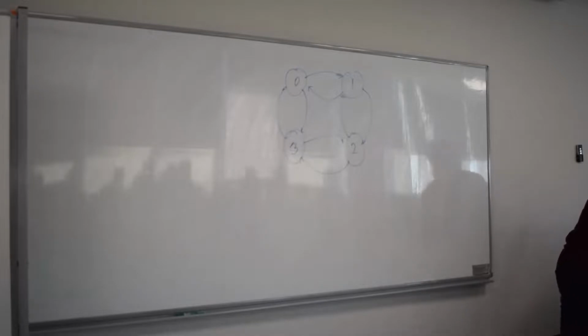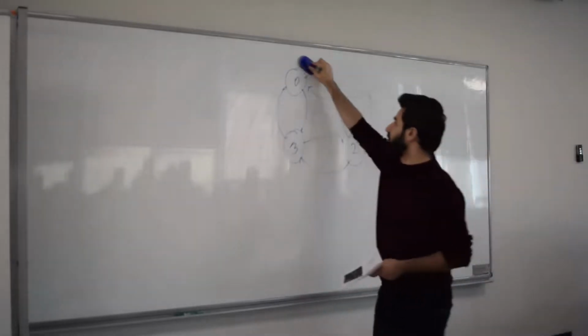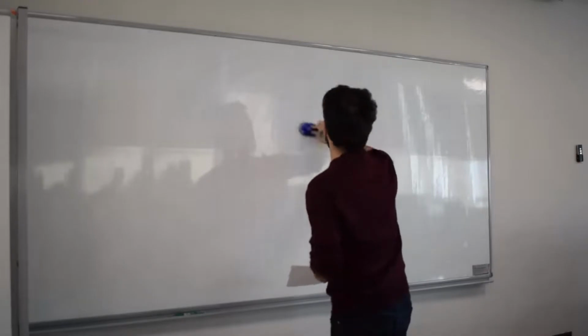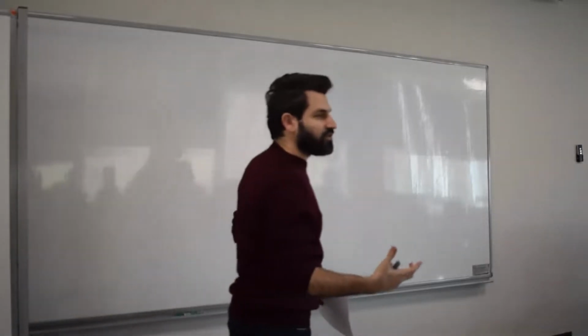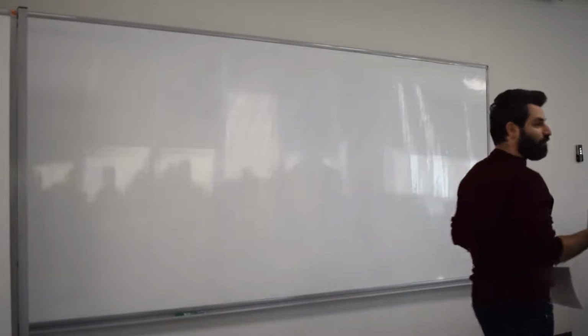But before that, I want to talk about registers, because in your CPU, you will use registers very much. Registers are used to store information, okay? And you already know how to store 1 bit using a flip-flop. So I'm going to stack these flip-flops right next to each other to create registers, because registers are capable of storing more than 1 bit.